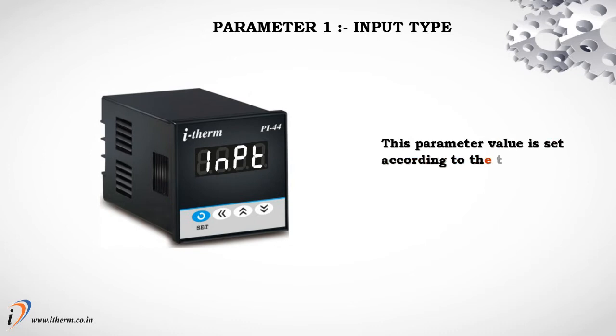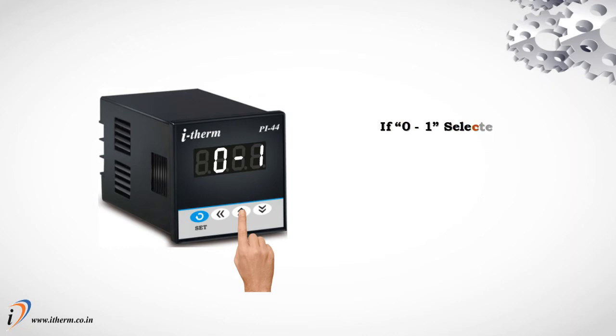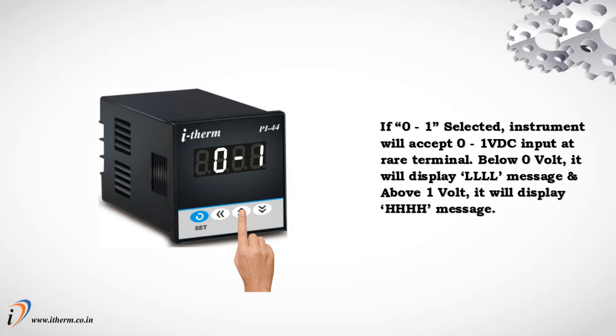Parameter 1, input type. This parameter value is set according to the type of sensor connected to the controller's input terminals. If 0 to 1 selected, instrument will accept 0 to 1 volt DC input at rear terminal. Below 0 volt, it will display L message, and above 1 volt, it will display H message.